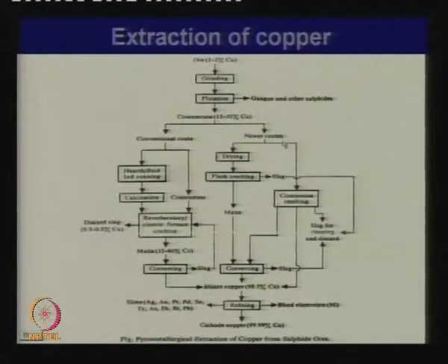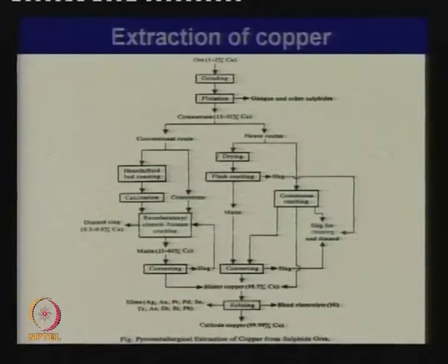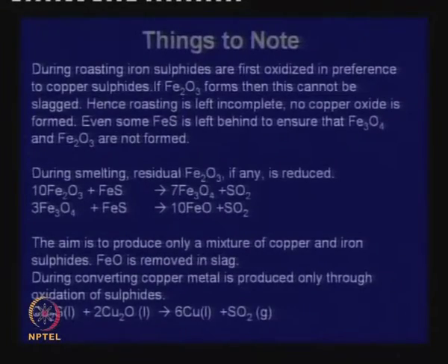When you go for continuous copper, then all 3 steps are combined. So, when steps are combined, your energy requirements become less. The steps are exothermic, but if you have too many steps, too many reactors, then there is a lot of heat loss. But when you combine steps, it is better from the energy point of view, and also the exhaust gases come out in concentrated streams. So, it can go for acid recovery.